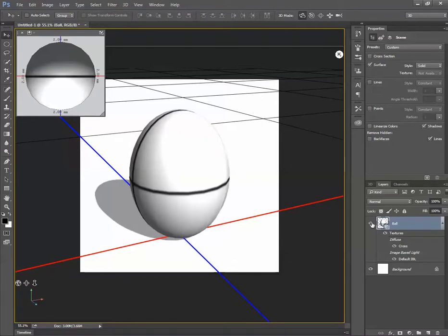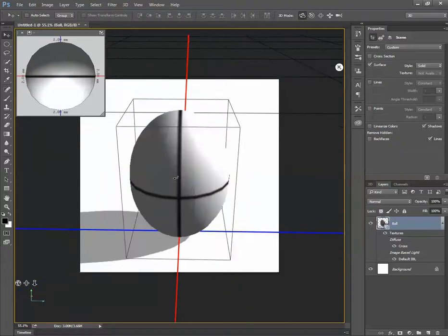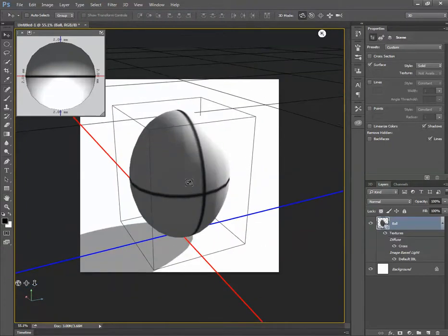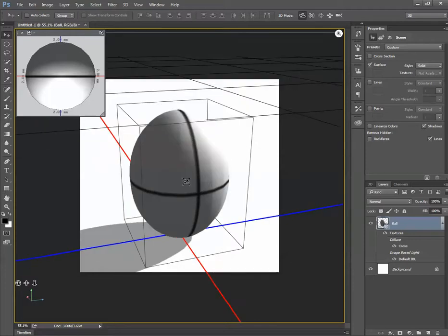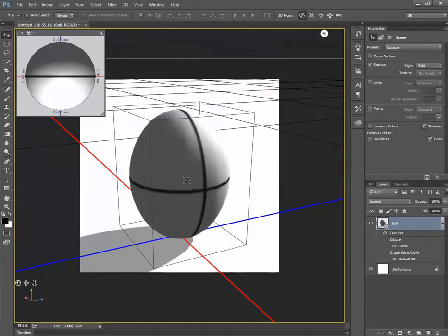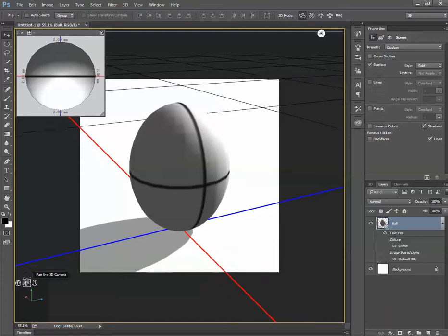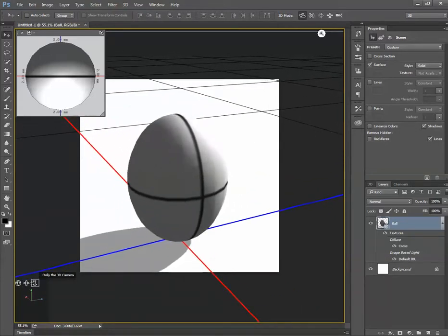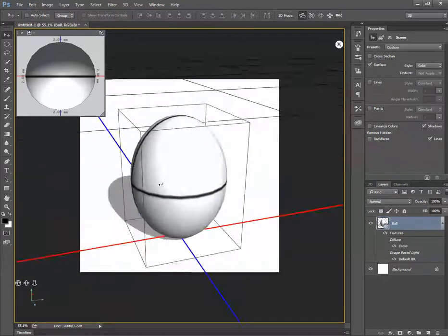And it's just a layer. It's just the same as any other layer. You can just turn it on and off. But it's using 3D space. The orbit tool is the object you'll get, the main viewport tool. Sorry. All your viewport tools are down here, so you can pan as well if you're using this one. So you can move around like that. We can zoom in and out as well using the zoom tool. So you can just use these three sets down here in order to manipulate it and get the camera to where you want it to be.